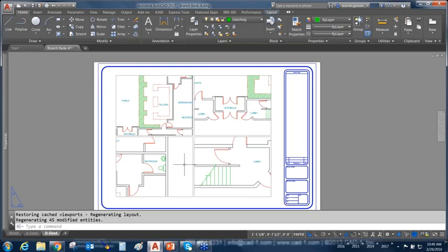The labels inside of Civil 3D don't have the multiple grips like I showed you here. You move one piece of a Civil 3D label, and it's going to move everywhere in every viewport. But, you know, it's got some pros and cons. It reacts to viewport twisting a little bit differently than the AutoCAD annotation does, and it works real easy. It automatically self-scales regardless of your scale factor, regardless of how many annotation scales you're plugging in. So there are pros and cons. Just understand that the annotative objects will work the same in any flavor of AutoCAD. However, those different flavors may have something in addition to or a little bit different from this.